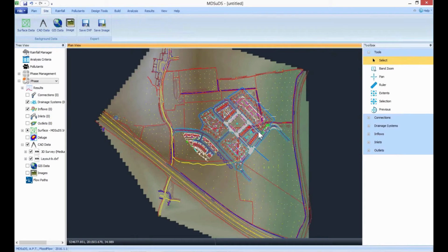And that's brilliant, but it's really useful to have this site survey information slightly beyond the bounds of the site, because what I'm going to do now is identify where the water wants to flow, and then I can use that information to help Dan, or maybe highlight if there's any low spots where the architect really wants to put a lot of housing and actually we're getting an awful lot of water accumulating in a sink spot, to maybe adjust the finished floor levels and such.